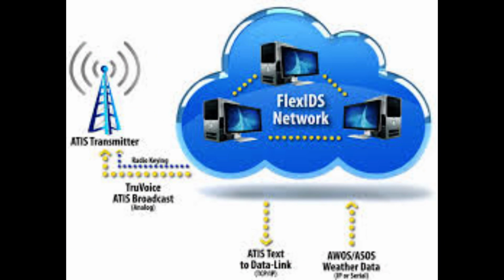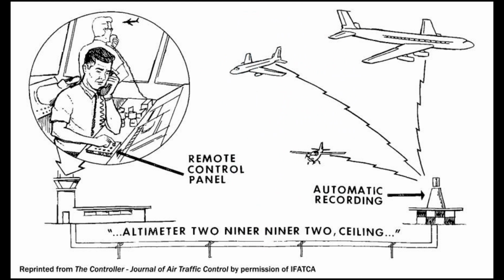Each ATIS report includes crucial information about runways and instrument approaches in use, specific outages, and current weather conditions, including visibility. Visibility is reported in statute miles and may be omitted if the visibility is greater than 5 miles. ATIS weather information comes from a variety of sources depending on the particular airport and the equipment installed there. The reported weather may come from a manual weather observer, weather instruments located in the tower, or from automated weather stations. This information, no matter the origin, must be from NWS-approved weather sources for it to be used in the ATIS report.